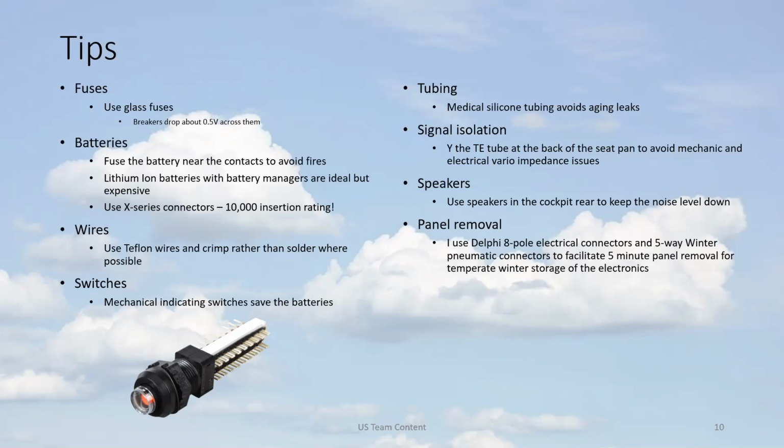When you're connecting up to speakers, I like to have the speaker pointing at me. If you look at my recent glider, I've got the speaker on the instrument panel at the bottom pointing right at me. So I don't have to have it up at 100 decibels to hear it against the other noise in the cockpit.